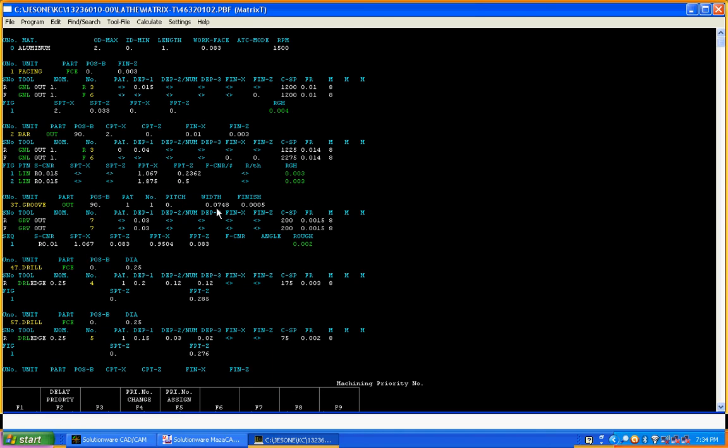And let me see, the width of the groove here is 74 thousandths and 8 tenths. So I always keep a 3/64 grooving tool in my machine, so I'm just going to say 50.